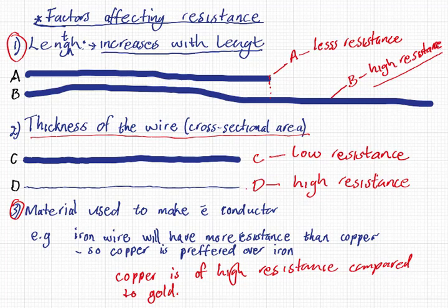And when the resistance is high, that means you are paying more money for your utility bill for nothing, because most of the electrical energy is going to be converted into heat. It's going to heat up this wire, and you are not supposed to be heating the wire. You want the electrical energy to work where it's needed, right? So you should always choose the shorter wire where possible.